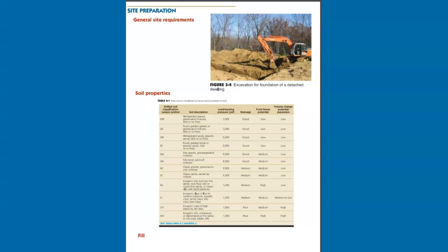401.4.1, where available data indicates that the soil may not be suitable for the foundation design, the building official is authorized to require a geotechnical evaluation and report prepared by an approved agency or registered design professional. Expansive, compressible or shifting soils have the potential to damage the structure. Highly organic soils, laden with decayed material from plants and animals, such as organic clays, organic silts and peat, are not included in Table 3-1 and are outside the scope of foundation design under the IRC.